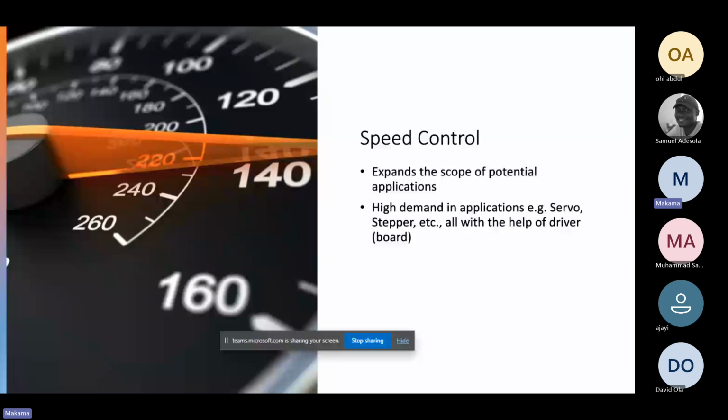What happens is that you need to make some combination of gears in order to gain high torque, because we know torque is force times distance. So you need to increase the distance between the immediate output of the motor, that's the head of the motor. You need to add some gears, small gears, big gears, do the combination properly. There are formulas to do that. Calculate the number of teeth required, do the calculation.